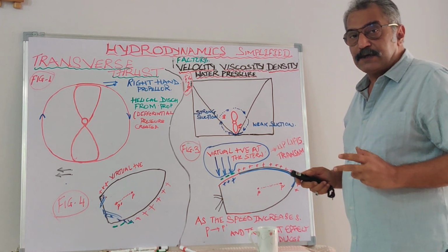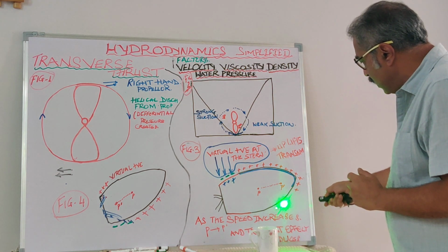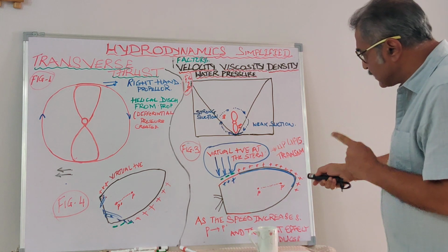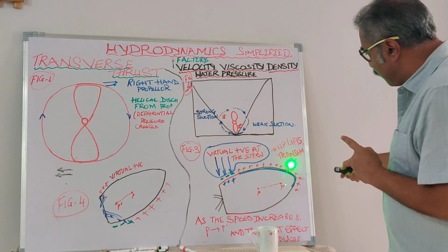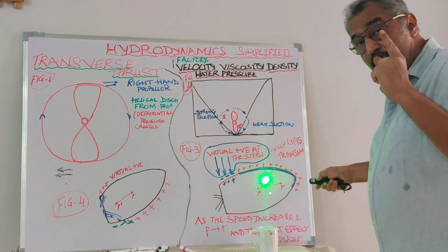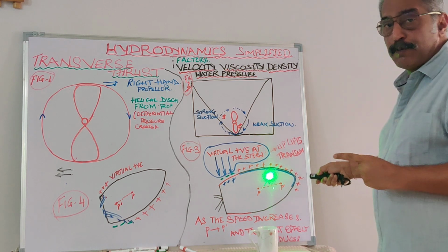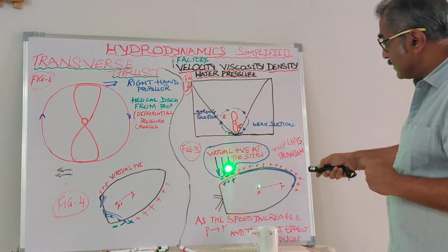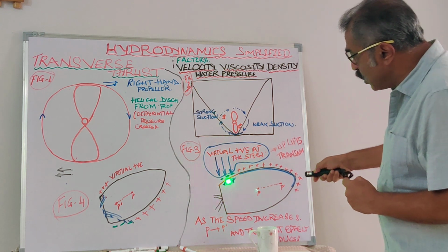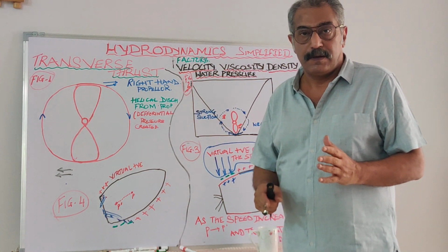the speed is increased. Once the speed is increased, all these positives will shift to the bow. They will be approximately in this curve. But till such time the speed is picked up, there will be a positive pressure here on this side, because the bow will start canting to port at a slow speed on a vessel with a right hand screw gaining momentum. Now, at the same time, see what is happening. There's a positive here also, but there's a virtual negative created here because of the propeller.